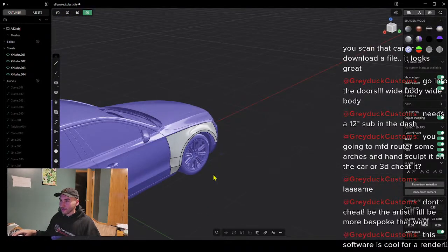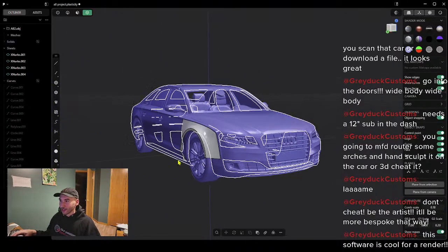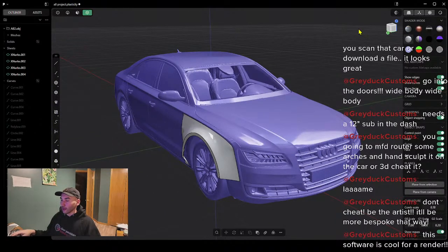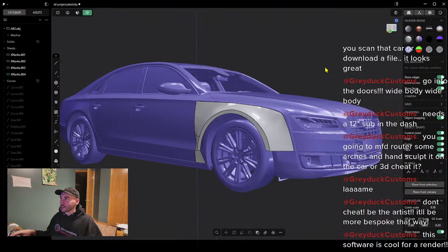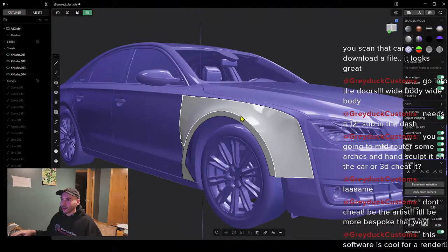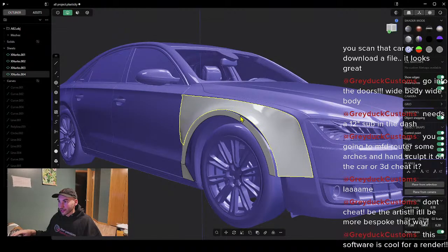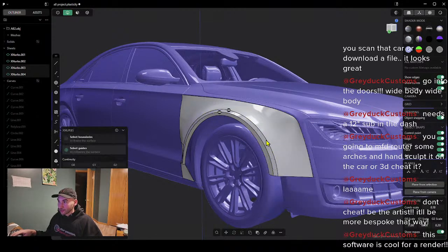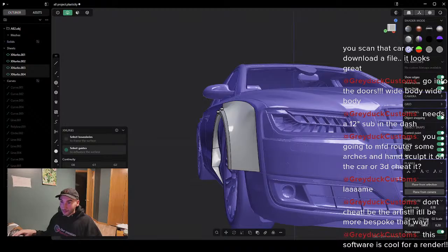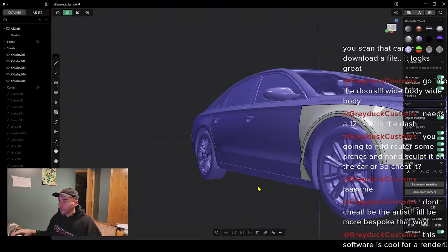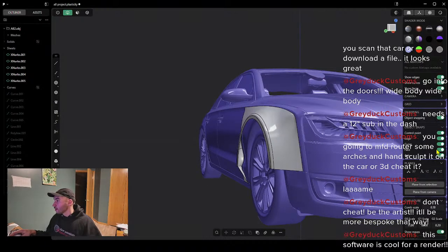And we'll see if the customer likes that design, or if he's got any opinions on how we can kind of change that up to make it look a little better. Like I said, I don't know if he'll like the square edge. So since we are here, let's go ahead and use that one technique where we select this edge, push it back a little bit. Select this edge, push it back a little bit. And we can even do it a little bit more than this edge and this edge, and use the xNURBS function with a G2 continuity, if it lets me. Yeah. And then we'll hide the edges.